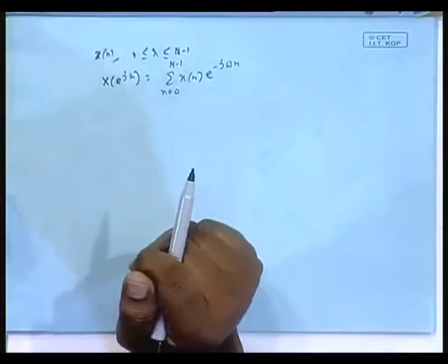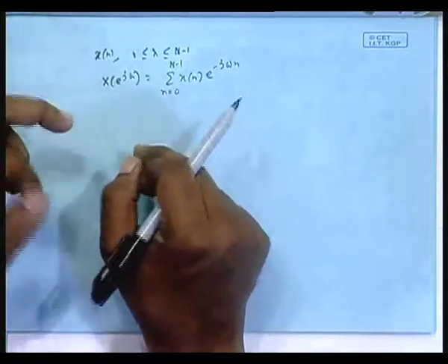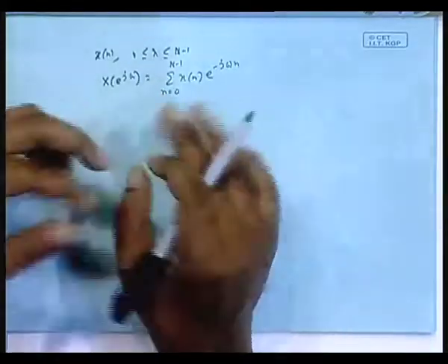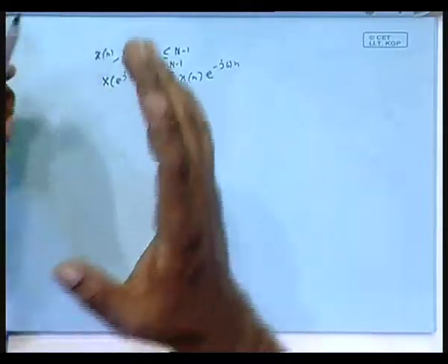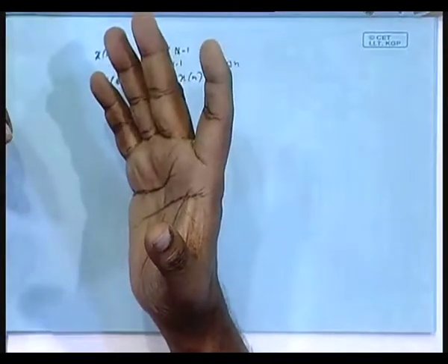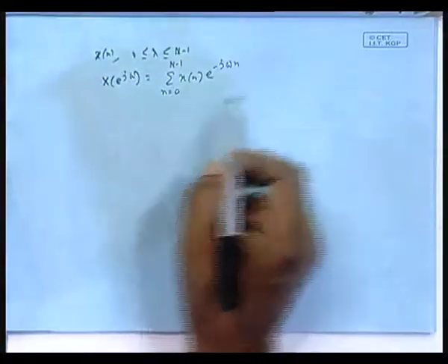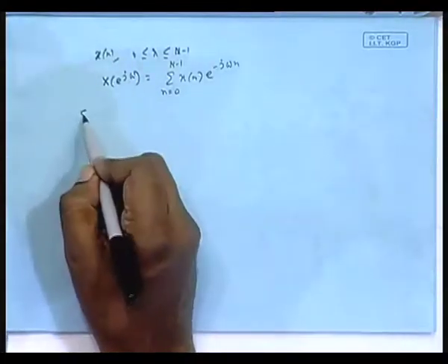Why? You can very easily see. Actually, this is one shortcut way of teaching DFT, but the actual way is, when I will be teaching vector space, then we will see that signals can be decomposed and written as linear combinations of basis vectors, a capital N number of basis vectors, and the choice of basis vectors gives you DFT or DCT or wavelet transform, Haar transform, Hadamard transform, all those things. But anyway, when I teach vector space, at that time again I might make some remark.